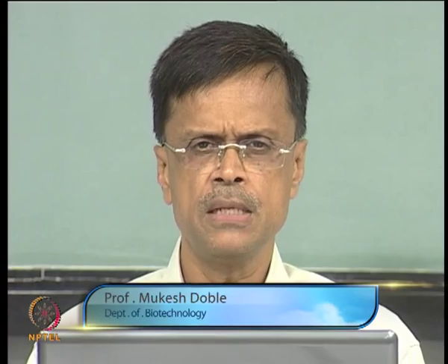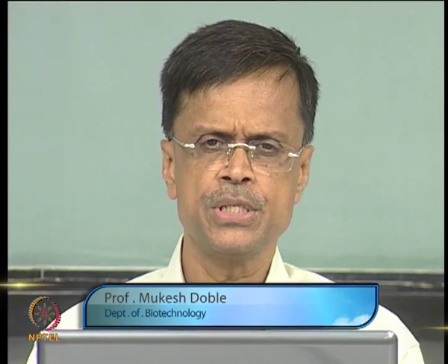Today we are going to do only problems. Doing problems related to mass balance, heat balance and separations help you to understand the various concepts in downstream processing. Downstream processing, as I explained in the previous class, is design of the cycle time, design of the dimensions of the vessels, deciding on the operating conditions like temperature, pressure, pH, flow rates and so on. So you need to do problems, then only you will be able to understand the concepts.